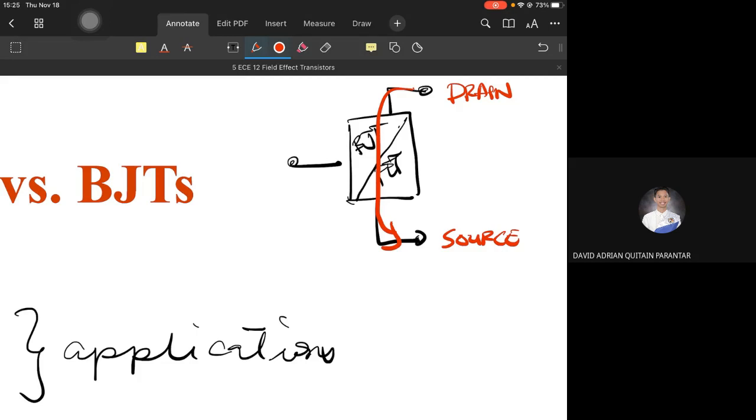It seems reversed, sir. Like with a faucet, the drain is the outlet and the source is the tap, right? Because the electron flow is really from source to drain. If you consider the electron flow, it's always from source to drain. But we're not considering the electron flow but the conventional current flow, which doesn't make that much difference if our objective is to analyze its application in circuits. So, following conventional current, current will flow from the drain to the source.